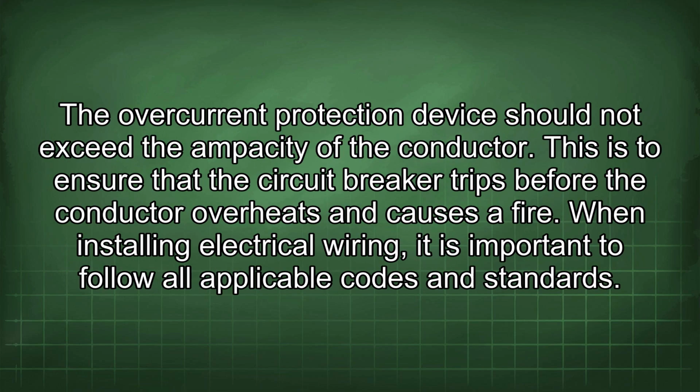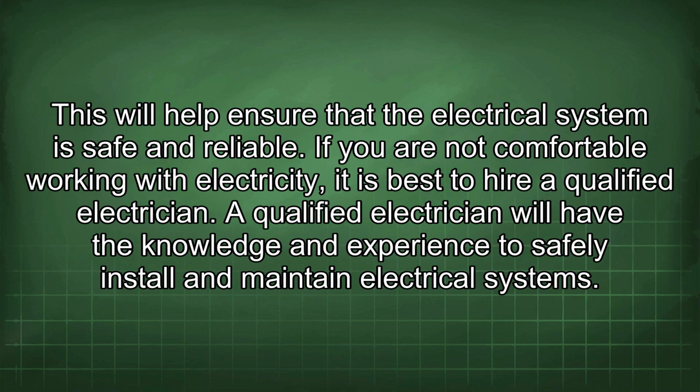The overcurrent protection device should not exceed the ampacity of the conductor. This is to ensure that the circuit breaker trips before the conductor overheats and causes a fire. When installing electrical wiring, it is important to follow all applicable codes and standards. This will help ensure that the electrical system is safe and reliable.